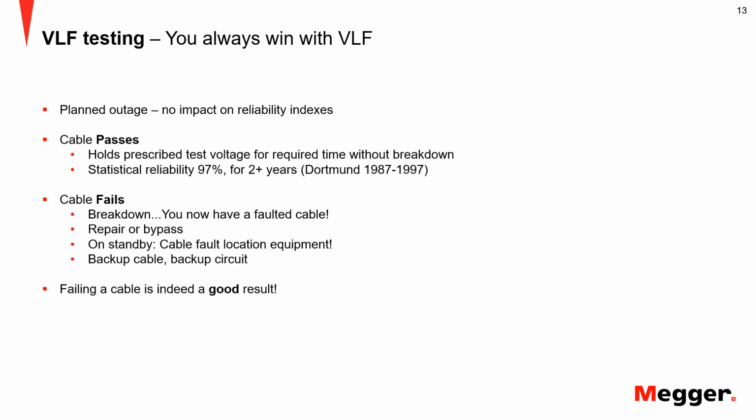And hopefully you have your cable fault locating equipment on standby, because then you could go out and connect the search generator, the TDR and everything to immediately fault locate, find the fault and repair it. Or you have a bypass, backup cable, backup circuit ready just to do the switching in time, and then you come back later and repair the cable later. So failing a cable during a VLF test is a good result. It's not a bad result.